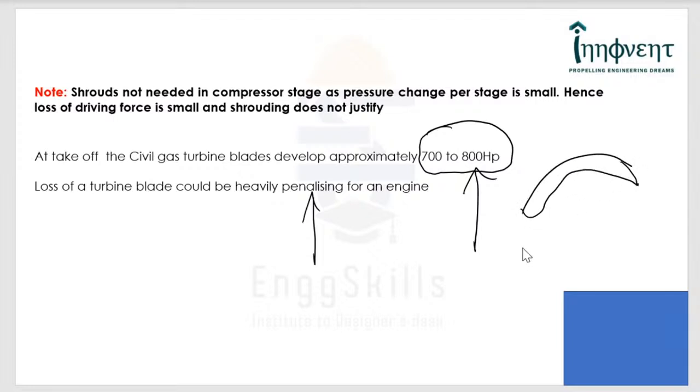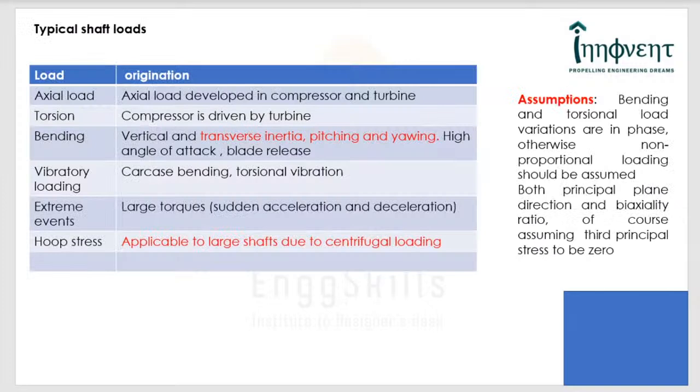When I say camber, it is essentially the total deflection of the flow, incoming and outgoing, and that means that you can extract maximum power in one single stage of the turbine, but you can provide very little power in one stage of compressor. And that reminds me of one of the famous principles of fluid mechanics, which says that it is always easier to accelerate a flow than to decelerate.